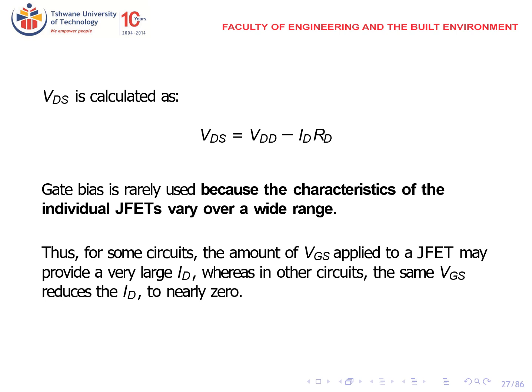VDS is calculated as VDS equals VDD minus ID RD. Remember, VDD is our supply voltage. We have a voltage drop on the resistor RD, and we also have a voltage drop between the drain and the source. So meaning that VDD equals ID RD plus VDS. That's how we got this formula.